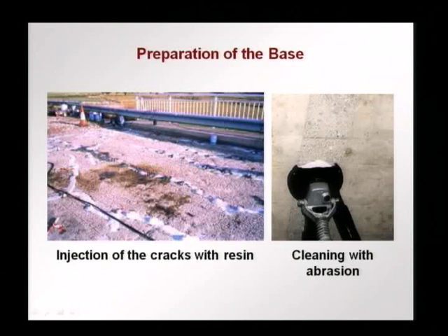Before a surface can be used, all cracks should be filled up. So any cracks, this would be say the top of a bridge deck, all cracks, if this is going to be reinforced with FRP, should be filled up. You cannot have a discontinuity on the surface, otherwise there will be a stress concentration at the crack and there will be a delamination starting off from the crack along the adhesive between the concrete and the FRP. So all cracks should be filled up, they should be injected with an appropriate resin or other material, such that when you bond the FRP, you are bonding over a uniform plane surface and not a cracked surface.